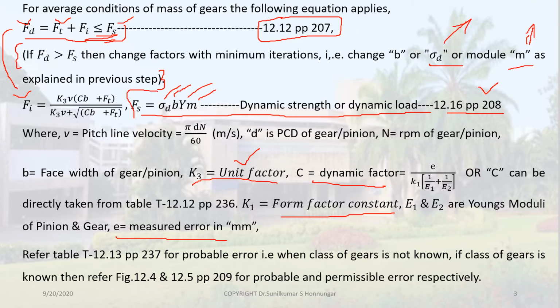Or else, most of the time for both cast iron as well as carbon steel, Young's modulus will vary somewhere from 200 gigapascal to 210 gigapascal. You have the liberty to take 200, 201, 202, 203, 204, 205, any value for that matter, since it is an assumption. But in your professional career, you can't do that. You have to get this particular Young's modulus from the supplier, or else ultimately you have to do specific testing.